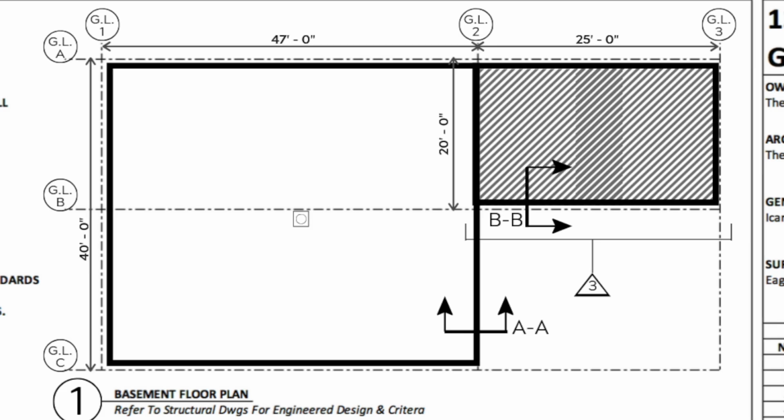Now let's talk about the visual parts of the drawing and what they represent. As we briefly covered before, construction drawings are made up of a series of details, which can also be described as a series of viewpoints and perspectives. On drawing A101 here, detail number 1 shows the basement floor plan. This plan view drawing shows the dimensions of the main house's foundation along with the garage's slab on grade foundation.